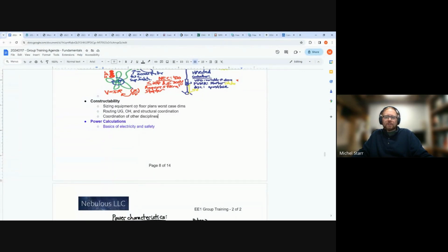I gave an example of constructability of even designing products that can be purchased, like that 1200 kVA UPS that maybe can't have a 4-wire output, just depending. What we usually do is take 3 or 4 of the predominant manufacturers. We just get their worst case dimensions, and that's how you decide how big of a switchboard to put on the floor plan. That way, when it's competitively bid, you're sure that all of the manufacturers will fit. And usually they're reasonably within the same sizes, but